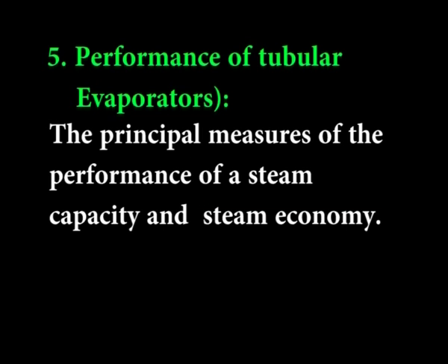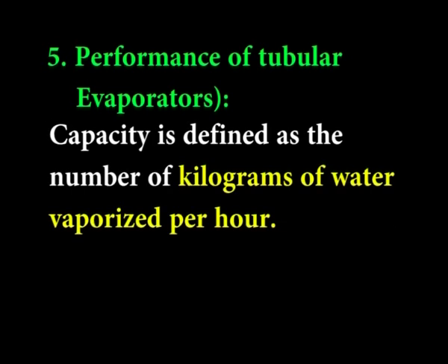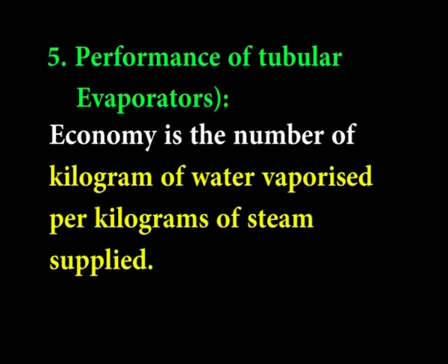The performance of the evaporators is judged by two principal measures, namely steam capacity and steam economy. Capacity is defined as the number of kgs of water evaporated per hour, while economy is defined as kgs of water evaporated per kg of steam supplied.